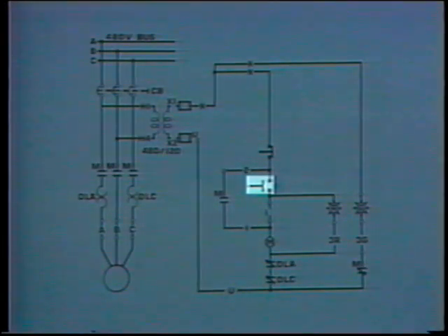But if the malfunction were in the start button, the green indicating light should still light. There would still be a complete circuit through the green indicating light even if the start button were malfunctioning. So the start button probably is not causing the malfunction. If the maintaining contact were not closing, the motor would run as long as the start button is held in. It would stop operating when the start button were released.